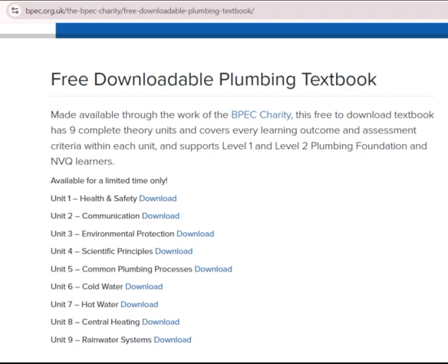This combination unit provides basic learning in the installation, maintenance, decommissioning and soundness testing of a basic range of wet central heating system / component types in dwellings and industrial / commercial properties, of similar size and scope to domestic dwellings. The unit covers systems in buildings up to 3 stories in height and with systems up to a maximum of 40 kilowatts heat output and pipework up to 32 mm diameter.